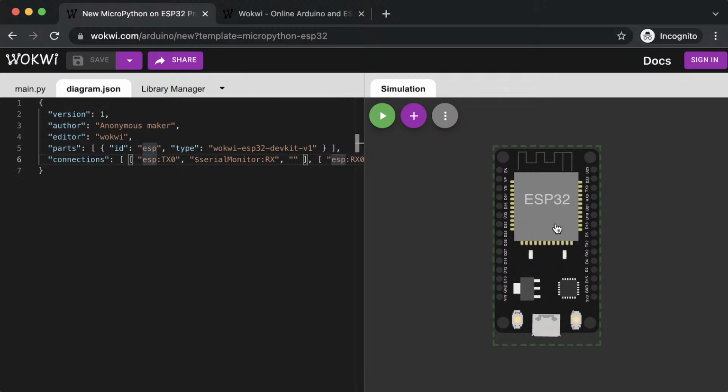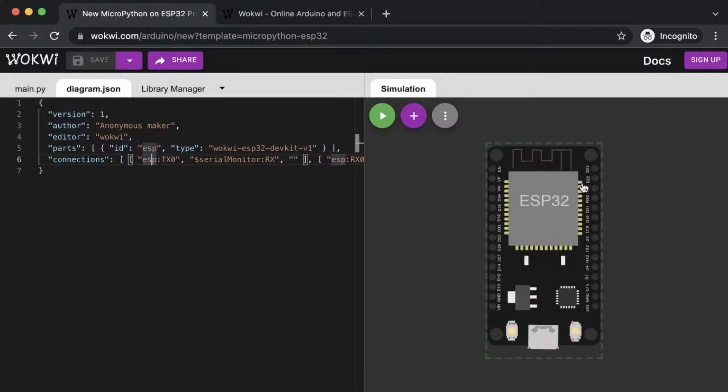So this SoC is the ESP32 microcontroller, and the entire black PCB that you are seeing is the development board. Why was there a need for this development board? See, these are the actual pins on the chip, okay, on the microcontroller. These are the gold pads that you can see. We cannot solder wires directly to these pads. These are very small, and also if you provide more heat to that, the copper layer will get corrupted and all that stuff. So it's not advisable to solder directly to those pins.